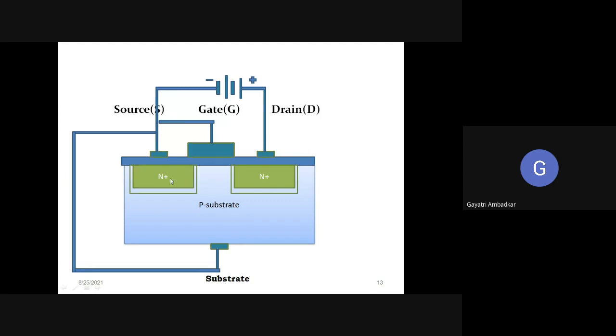So what will the source do? It will provide the electrons. Electrons will be pushed from here and drain will attract these electrons. Once the flow of current is established; right now there is no current established. So remember that you have to make drain positive with respect to source. Can anybody tell me, if it is a P-channel MOSFET, what shall be the polarity of the drain?